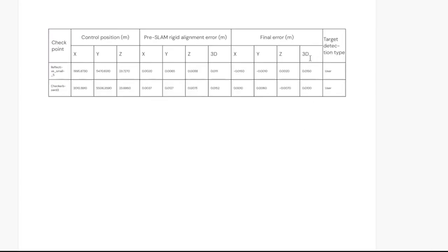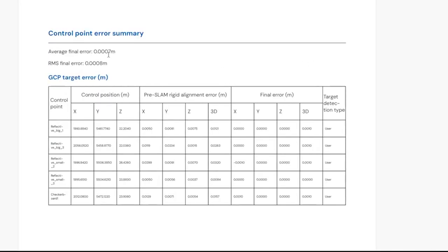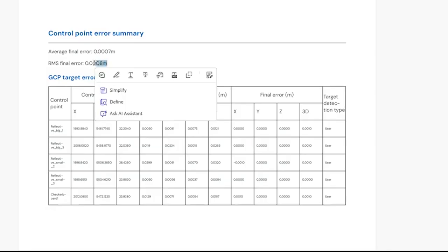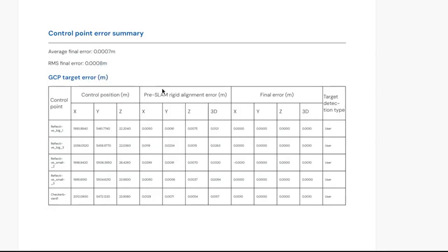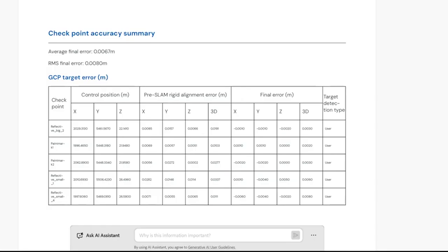And that's the continuation. And the last part is the control point error summary. So the RMS error for the control points was less than 1mm. Typically we see this because we're actually constraining the point cloud to these positions. So usually these are pretty good, and the checkpoint errors are a better independent check of the accuracy from the point cloud itself when comparing against those total station measurements that we got while out in the field.